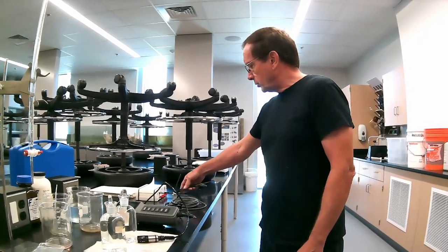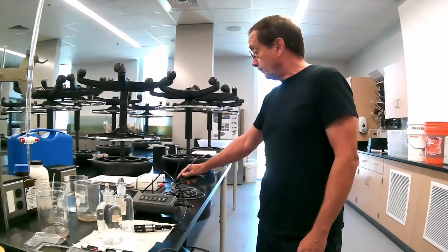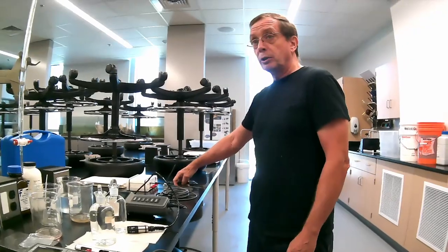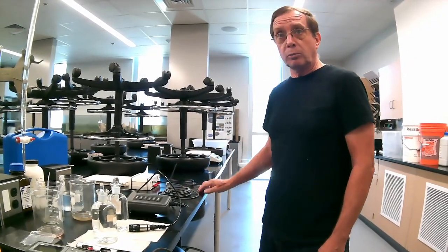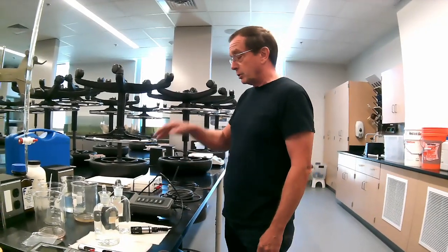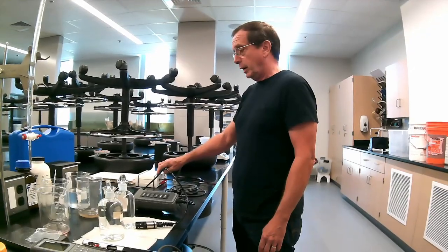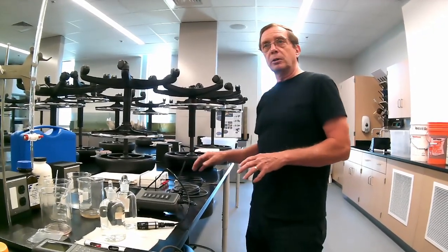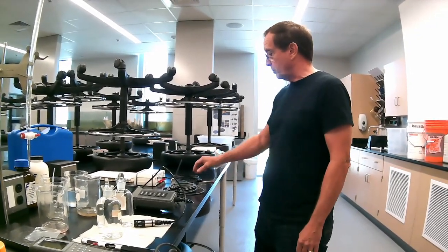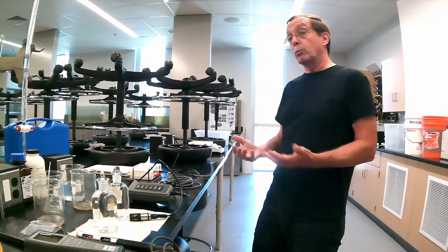You can calibrate this Witrox electrode, our optode, and once you've done that, it's good for probably 3 to 4 weeks before you have to calibrate it again. Now the newest ones, which we don't have, this is third generation technology here, and they recently came out with some improvements. One of the improvements was the new optodes are self-calibrating, so there's no calibration needed.